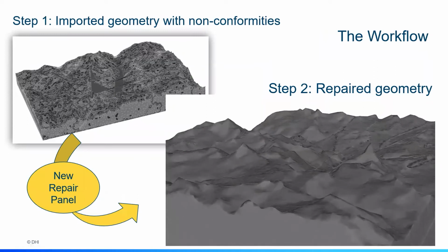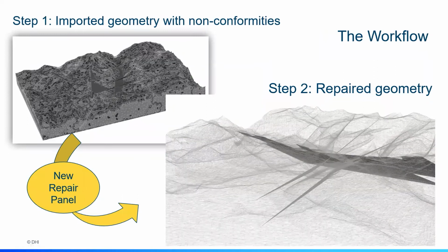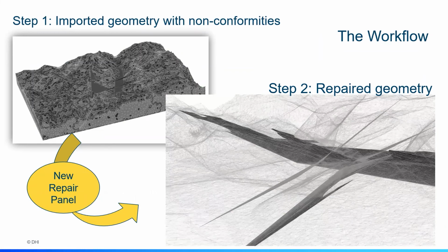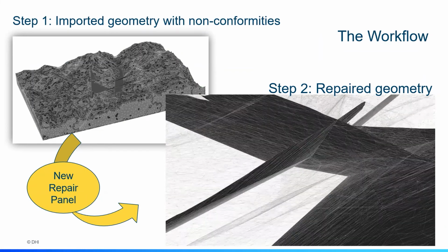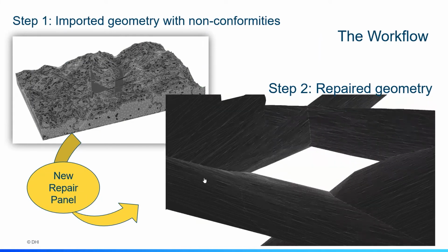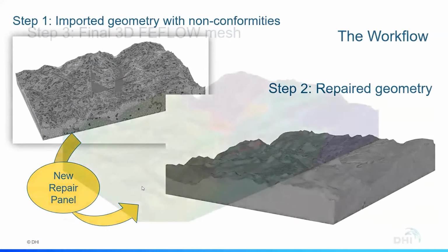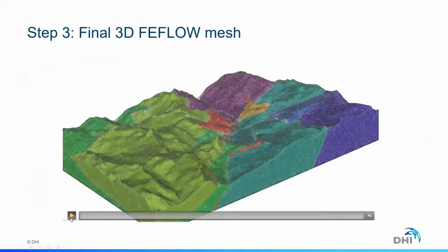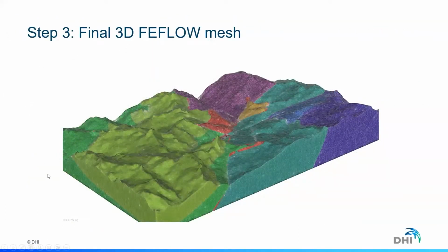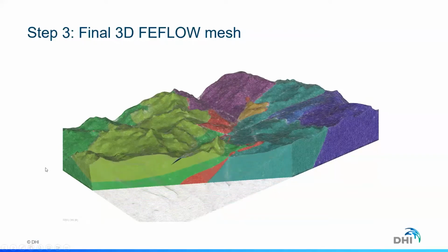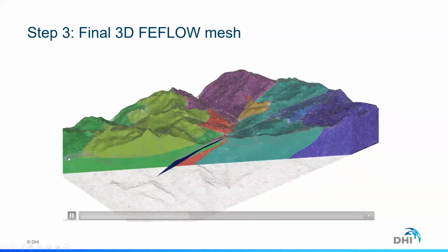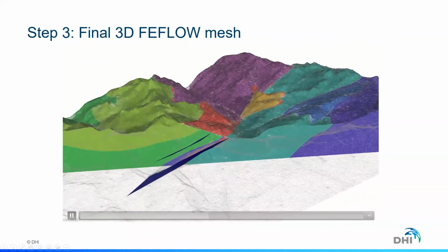The procedure will look at all the different surfaces, how we pass it, and we'll make sure that we fix all the self-intersections and improper data in the outer and inner faces. And when the data is ready, this increases the chances to create 3D fully unstructured meshes, like the case that you see here.